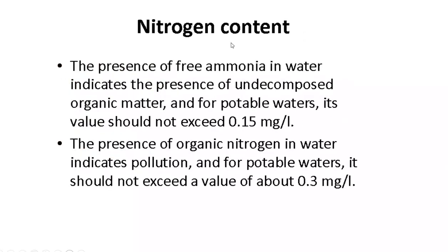Regarding nitrogen content, the presence of free ammonia in water indicates the presence of undecomposed organic matter, and for potable waters its value should not exceed 0.15 milligram per liter. The presence of organic nitrogen in water indicates pollution, and for potable waters it should not exceed a value of about 0.3 milligram per liter.